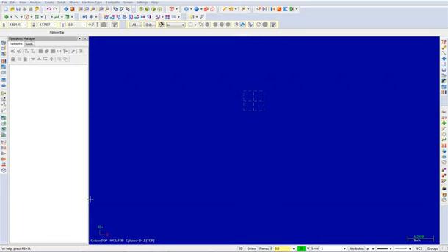We will begin creating our geometry. Select the Create Line Endpoint command. Input a length of 0.7 at an angle of 90 degrees. Now select the fast point icon and enter in the coordinates 0, -3 and press enter. Select the OK button to exit this command.